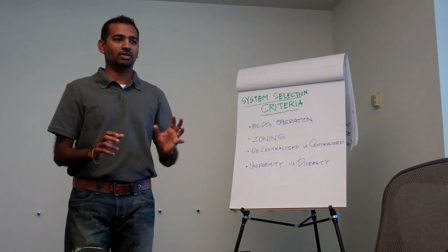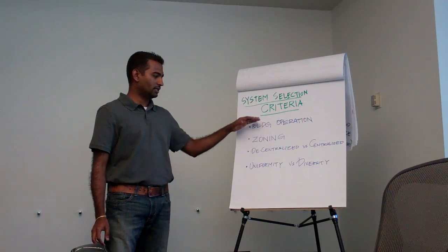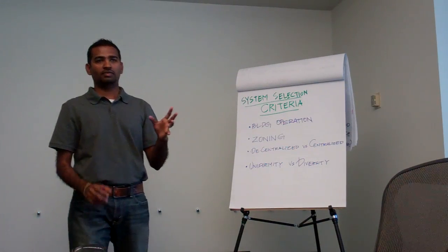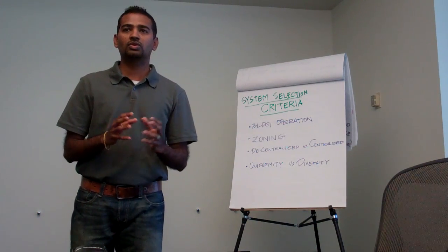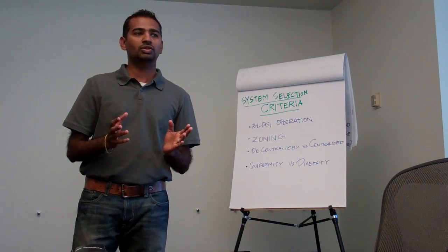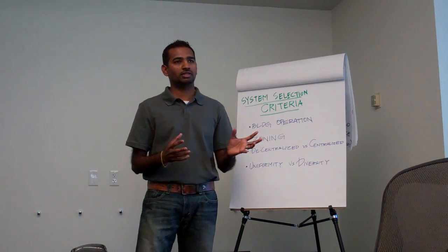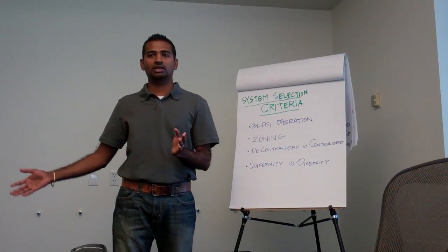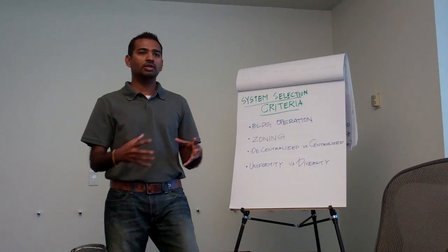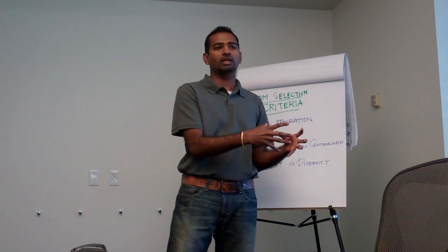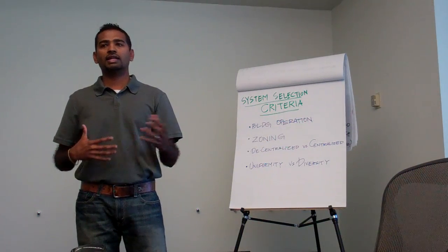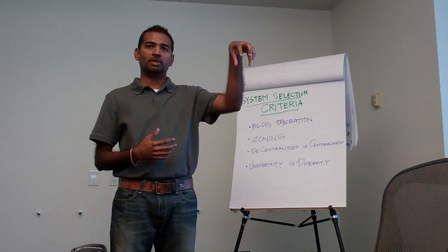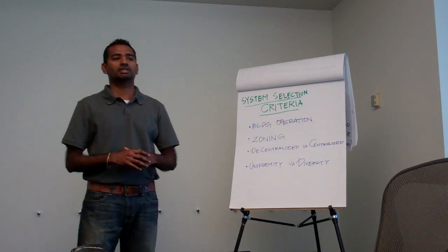So the simple way of looking at system selection criteria are these 4 items. The first one is trying to understand building operation. I'll give you an example. If your school district decides to use the gymnasium in your project 24/7, I mean during all the weekends in a year, then you do need to control that separately than the rest of your building. So in that case, will hooking up the conditioning for the gymnasium to a central plant make sense or not?